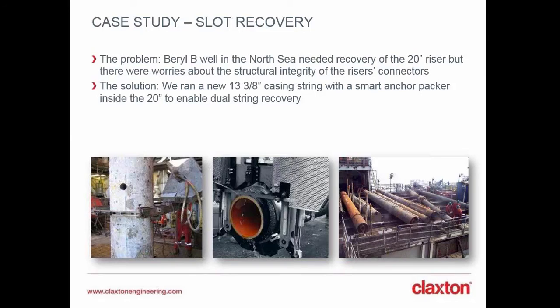So what we did was supply and run a 13 3/8 casing string complete with a smart anchor packer inside a 20-inch tieback, an internal dual string recovery. That internal casing riser provided structural strength and integrity to the 20-inch riser, so as to be able to retrieve it safely.